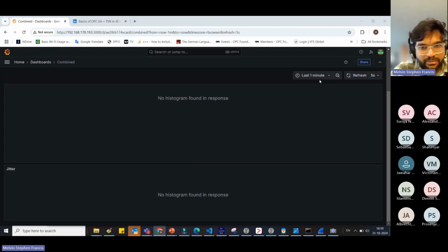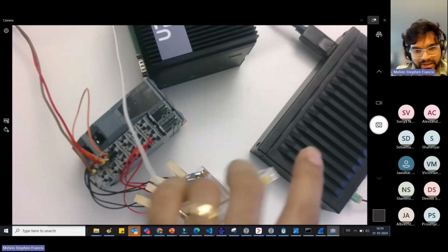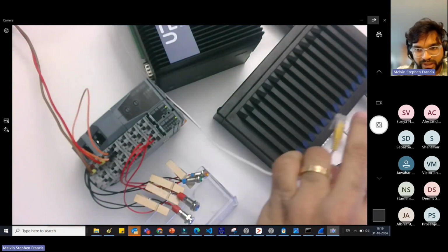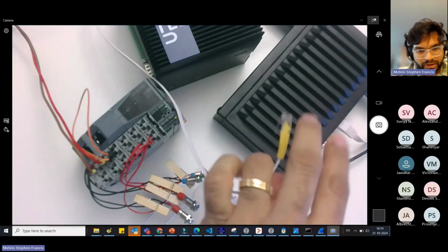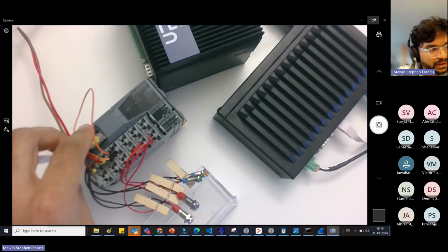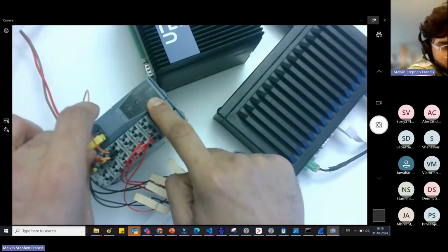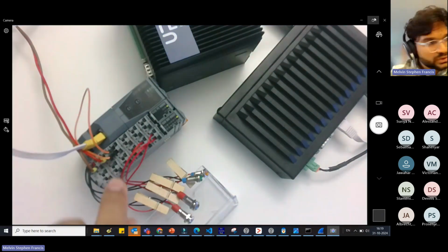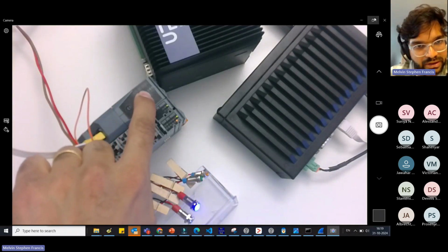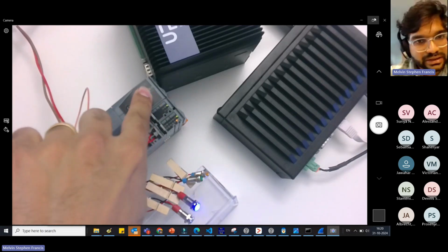And now I'm going to connect this particular Ethernet cable that comes from here. So you can see this white flat cable. The same white flat cable from the TQ systems is going to be connected peer to peer to this particular B&R bus coupler, which runs OPC FX, and I'm going to connect it here. So this particular LED that is blinking is the time synchronization. It has settled down, and it shows that it is in time sync.